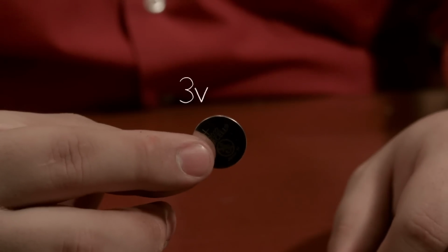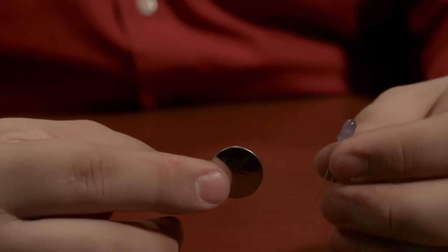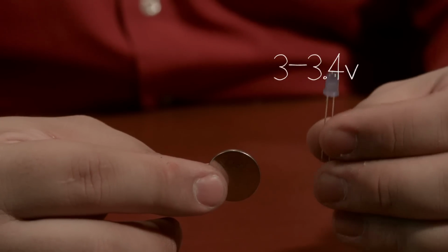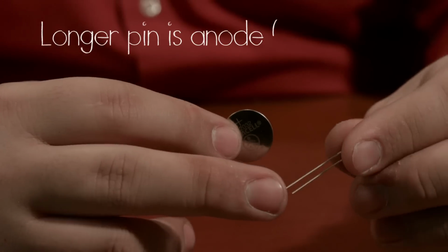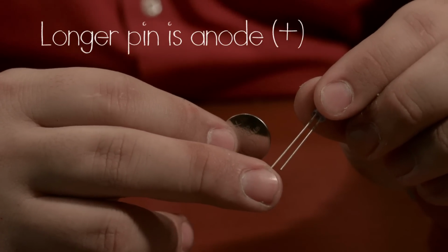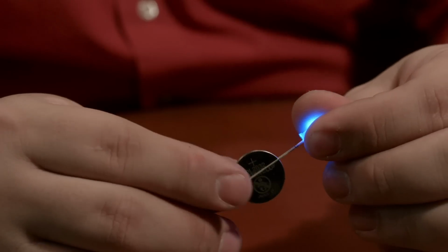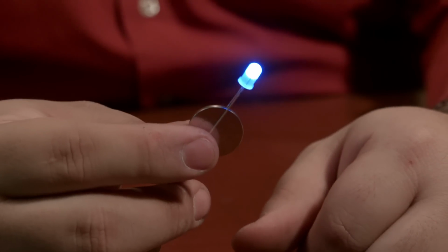So let's make a very simple LED circuit. Here I have a watch battery. It's rated for 3 volts. This blue LED has a forward voltage rating of between 3 and 3.4. Now we'll just take this LED and put the longer pin, or the anode pin, on the positive side of the battery and the shorter pin, the negative or cathode side, on the negative side of the battery. So we'll get that right there. And bingo, we have an LED light. This is about as simple a circuit as you can make.